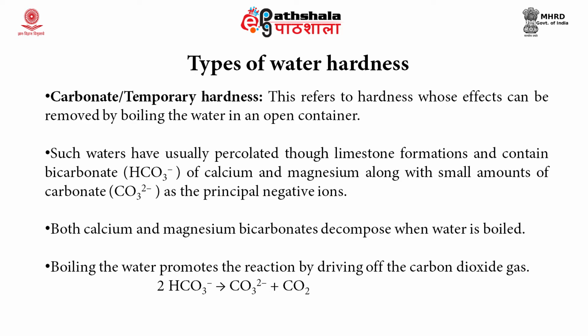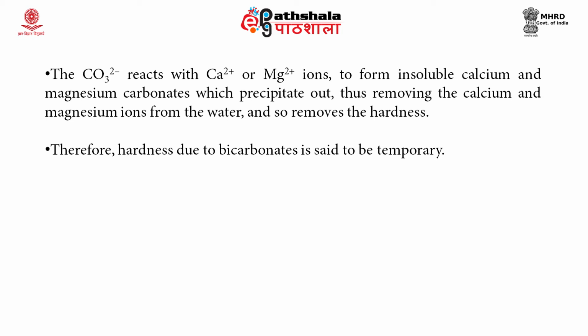So, boiling of the water promotes a reaction and the carbon dioxide which is evolved leaves the water. The carbonate reacts with calcium or magnesium ions to form the insoluble calcium and magnesium carbonates, which precipitate out and form scales on the surface. Thus, the calcium and magnesium ions are removed from the water, and so is the hardness. Therefore, hardness due to bicarbonates is said to be temporary.